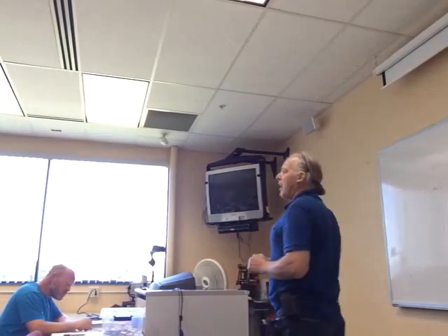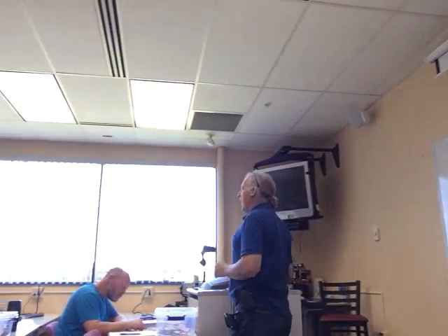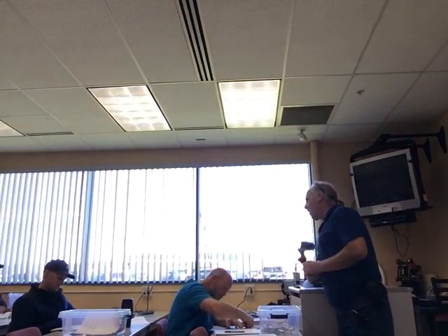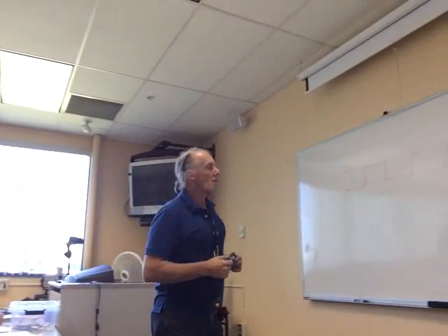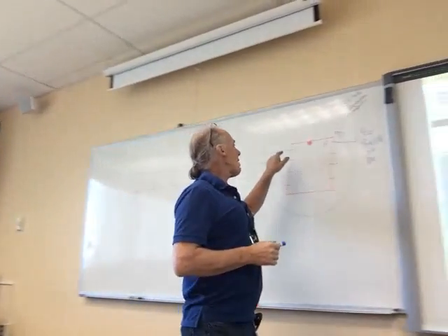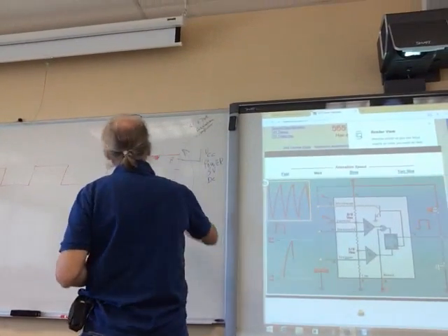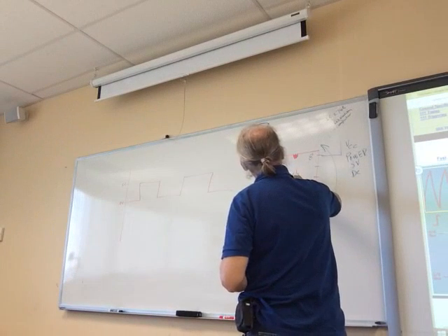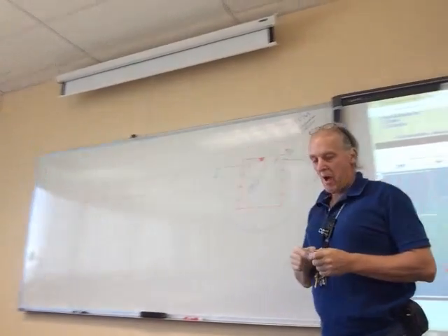For those of you in my class, you cannot put it on a voltage divider because it will consume more or less current over time, and it will change the voltage input if it's on a divider, okay? So, all right, so pin 1 is ground, pin 8 is power.